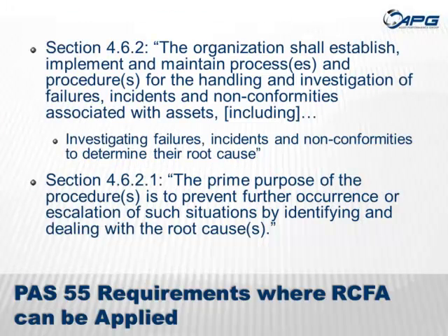So what does PAS-55 say about where root cause failure analysis should be applied? They've got a few clauses in their specification, which, if you'll permit me this one time, hopefully will be the only slide that I read to you. I'll just read these two sections. Section 4.6.2: the organization shall establish, implement, and maintain processes and procedures for the handling and investigation of failures, incidents, and nonconformities associated with assets, including investigating failures, incidents, and nonconformities to determine their root cause. Furthermore, subsection 4.6.2.1 states, the primary purpose of these procedures is to prevent further occurrence or escalation of such situations by identifying and dealing with the root causes.